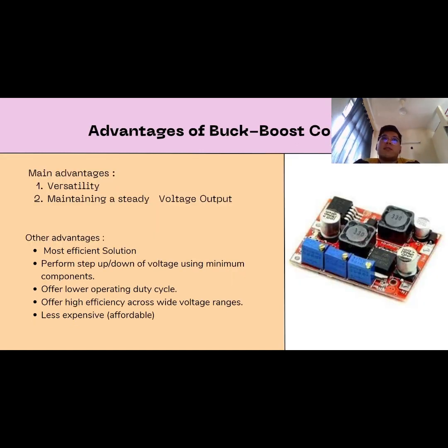The next slide is about the advantages of the buck boost converter. The main advantage is its versatility. It can increase or decrease the voltage as needed, which is very beneficial in various applications. Moreover, it is capable of maintaining a steady output despite changes in the input voltage, thus providing high efficiency and excellent response to load changes. The other advantages are on the slide, such as being affordable.